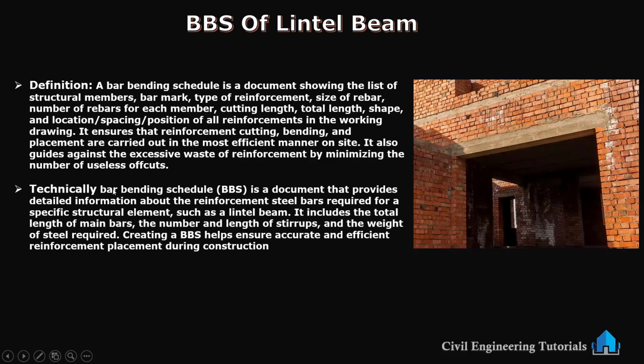Technically, bar bending schedule BBS is a document that provides detailed information about the reinforcement steel bars required for a specific structural element such as lintel beam. It includes the total length of main bars, the number and length of stirrups, and the weight of steel required. Creating a BBS helps ensure accurate and efficient reinforcement placement during construction.